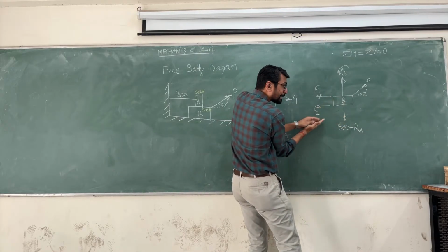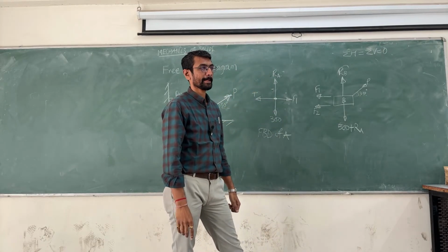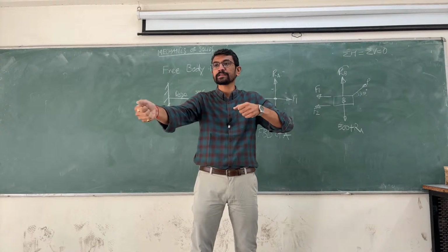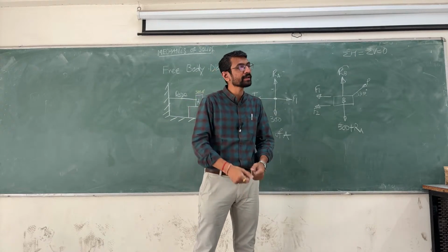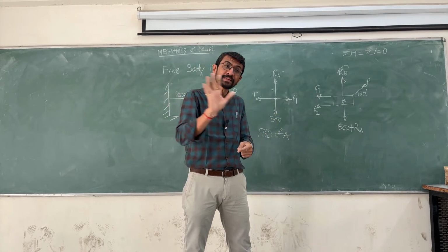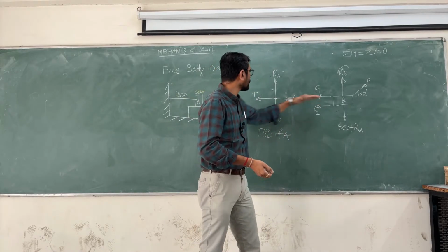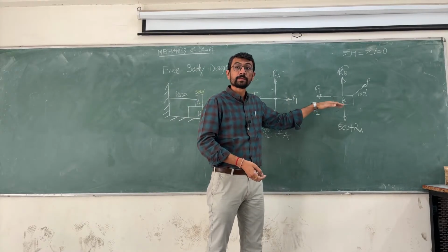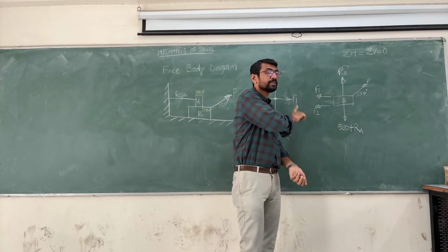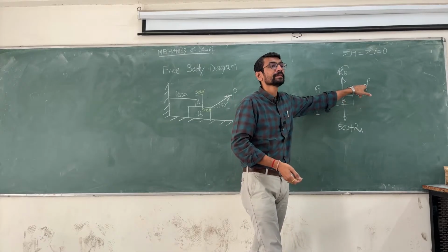If you did not understand this, I would call you up, call 3 more people, and pull from different directions and see that the body remains the same. It means that forces acting in their respective directions balance each other while keeping their direction. If it is friction, it will act in this direction, but the value of friction will depend on this. The actual question is not to draw the free body diagram, but to see up to which force P this body doesn't move.